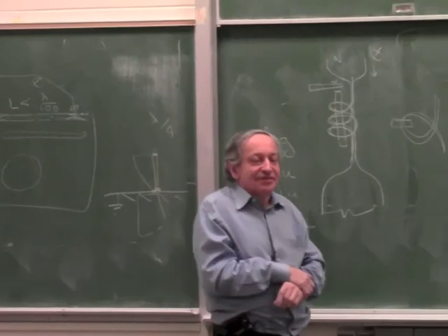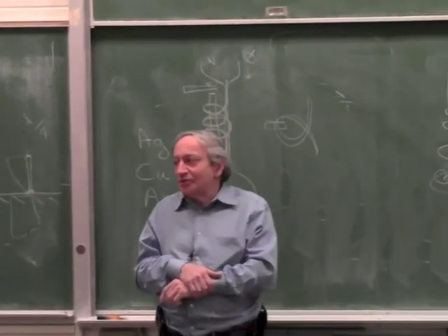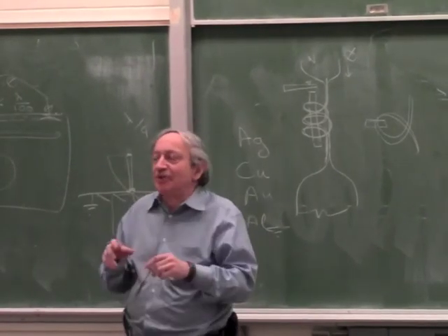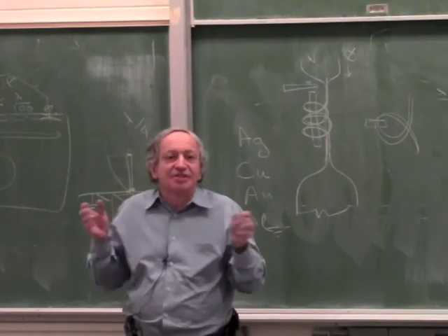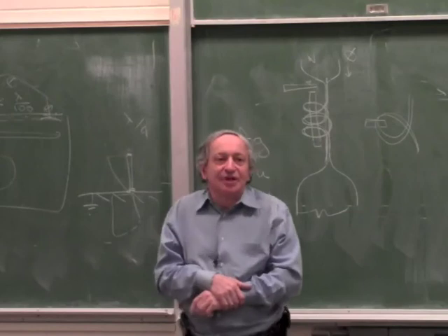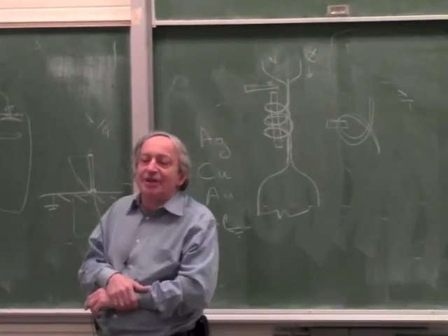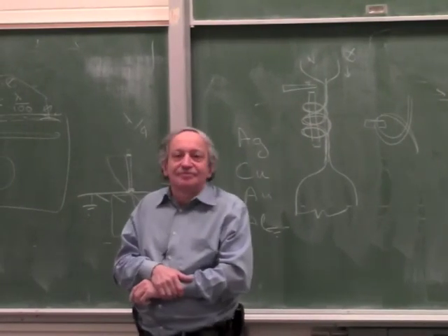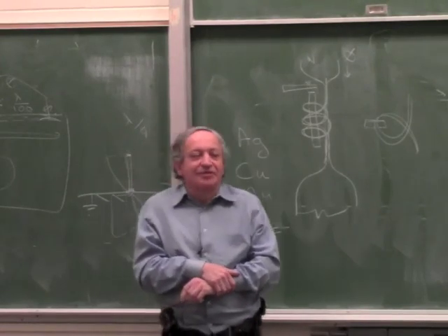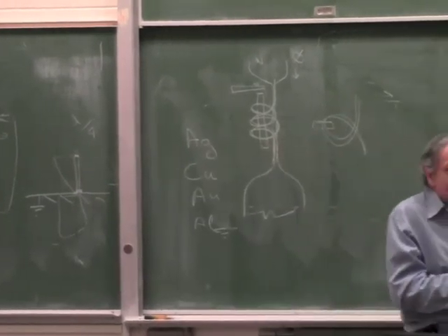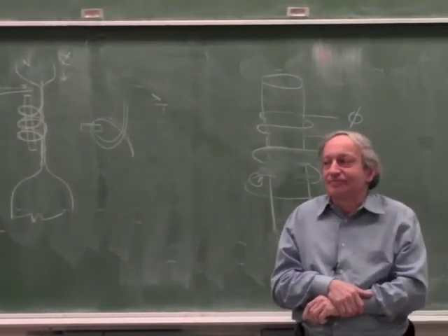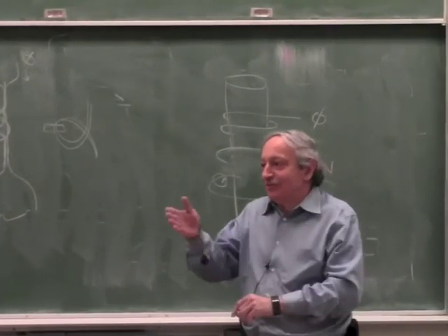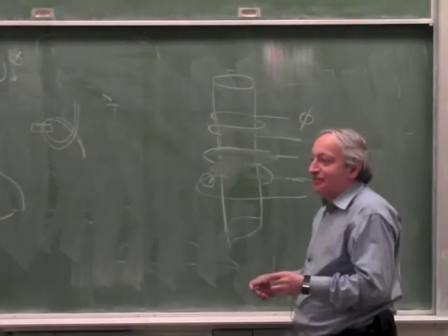But there is a third reason, because silver is also good for that. There's a third reason, especially why it's all silver plated. If you take apart some microwave equipment, it's always silver plated inside. So I understand gold we discussed, but why is everything silver plated in microwave equipment? A hint, it's related to an effect we discussed half an hour ago. Yes. Skin depth? Very good. Okay. Finally somebody is fully awake.